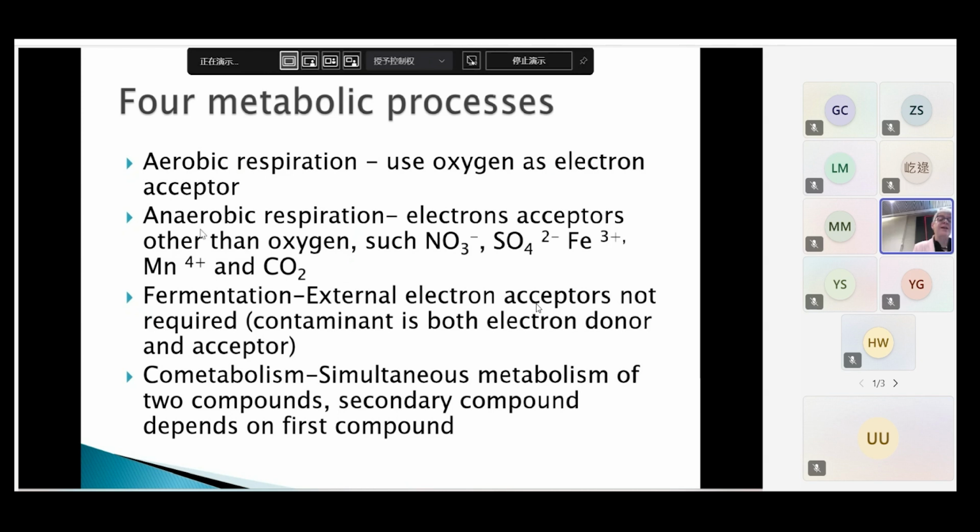Initially you had hydrocarbon contents of 3,700, and after time it went down to about 450. The benzene, toluene, and ethylbenzene levels were over 80 ppm, and over time they became non-detectable.